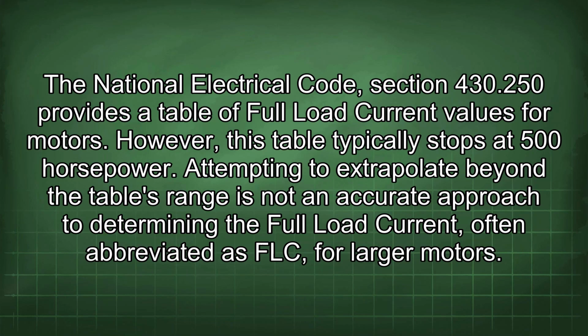The National Electrical Code, Section 430.250 provides a table of full load current values for motors. However, this table typically stops at 500 horsepower. Attempting to extrapolate beyond the table's range is not an accurate approach to determining the full load current, often abbreviated as FLC, for larger motors.